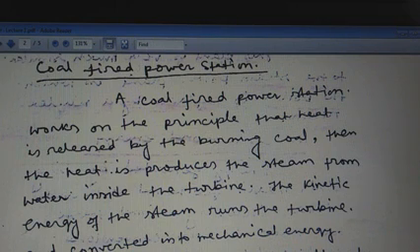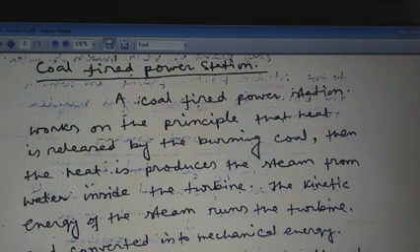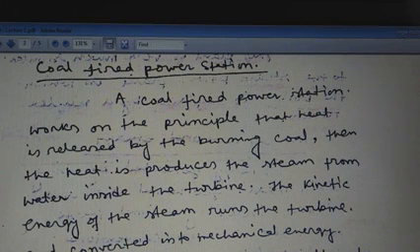The superheater converts the normal steam to superheated steam. The flow rate of superheated steam is very high compared to normal steam. The kinetic energy of the superheated steam runs the turbines. Then the kinetic energy of the steam is converted into mechanical energy inside the turbine. Here the turbine is coupled with the alternator or AC generator, which produces electrical energy. Then this energy is connected to the transformer to create the proper transmission voltage.